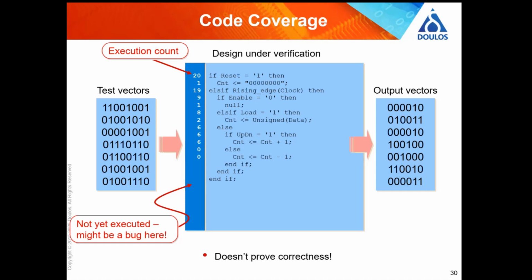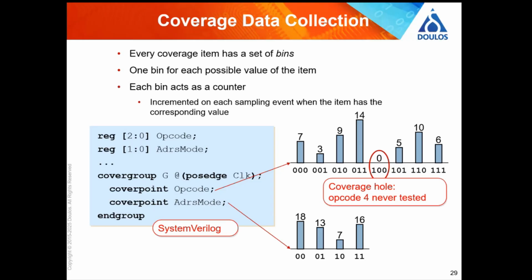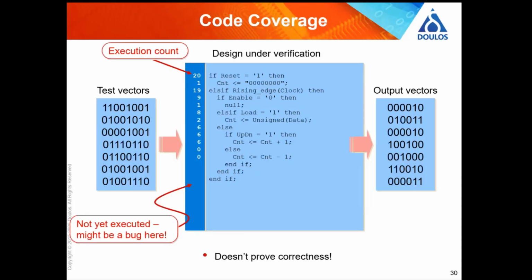But something really important to point out, both with this idea of code coverage, which your simulator can do, and what's called functional coverage, is that just because you've done the thing doesn't mean it's right. The checker is still important. Yes, you needed to have tested, you've done a read, a write, a jump, a store, whatever it is. You also need to check that that's happened correctly as well.